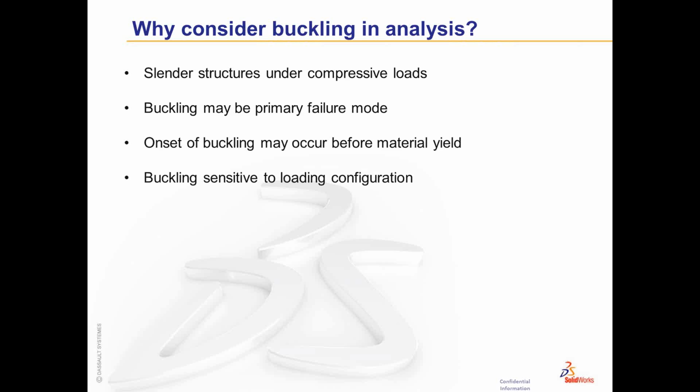So why do we consider buckling analysis? Buckling, much like fatigue, is something that is often disregarded or not taken into account, either because calculation of buckling would be difficult for real structures, much like fatigue would be, or the tools don't exist, such as there's no FEA tool in-house to be able to do the analysis, or it's just not considered.